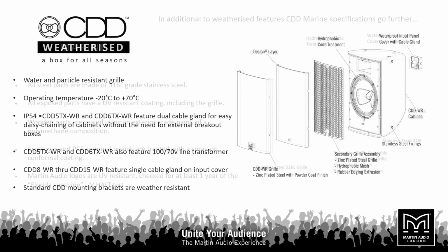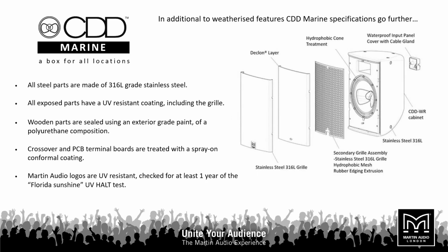Going into more extreme conditions, we have our CDD Marine, where all of the metal parts are replaced with stainless steel 316. And again, all of this hydrophobic treatment to the individual drivers and to the Declon as well. This is, of course, all UV treated. All of the metal components, which cannot be stainless steel, are encased in some kind of a plastic to stop any kind of corrosion or any exposure to the elements. And you can literally pressure wash these loudspeakers directly into the grill, and they will absolutely stand up to that and keep performing as you would expect.